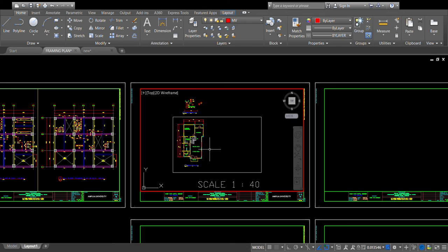Now press Z for zoom. Okay, now listen to this very carefully. Press control and then right click. Now select the endpoints. If you do that, you will select the corner of the paper inside. Don't worry, all rectangles here are scaled and good for the papers. Okay? And then, notice that I cannot select the other corner. So, control again, right click, and then you will notice endpoint, then you will have it.